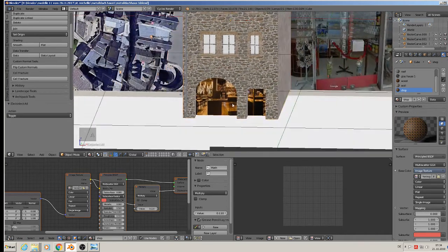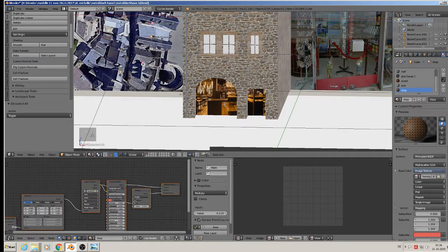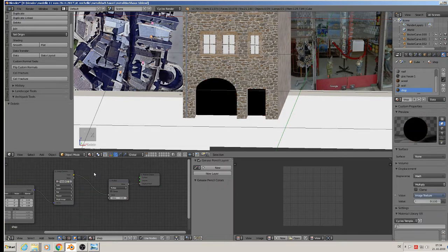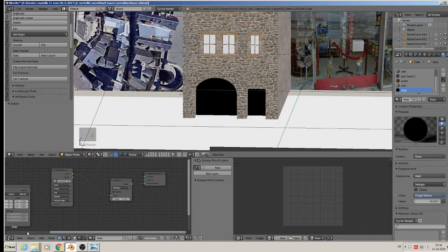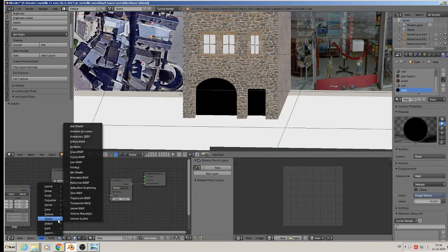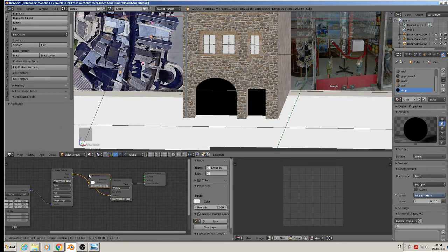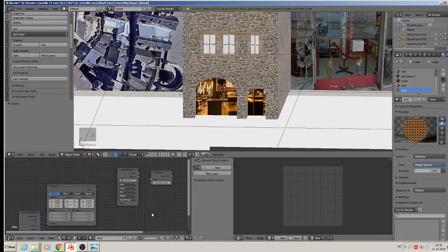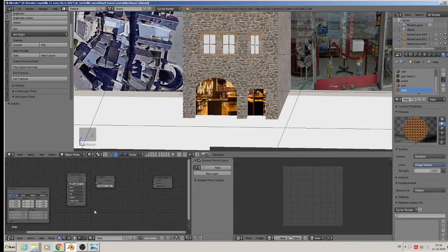When you render that now, that will be too dark. So we have to delete the principled shader and give here an emission shader. So shader, emission, and plug them onto the surface. We delete the multiply that we don't need. Good. All done here. File, save.